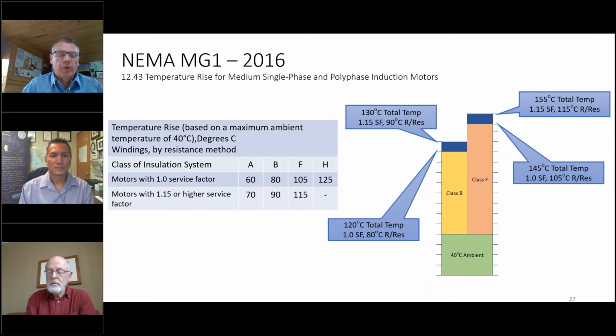Years ago, 20, 30 years ago, when VFDs started to come into play, motors were burning out quite frequently. Insulation systems have improved to handle what we call the dirty waveform, or non-sinusoidal waveform. And different manufacturers have better topologies or better performance on the output.